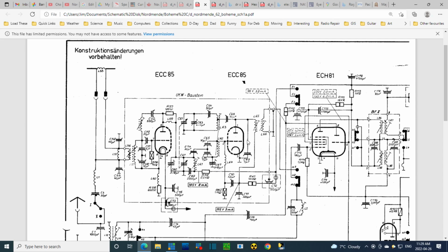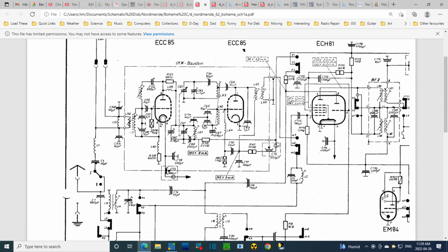Okay, so if we look at the grids back here, this is the FM tube here. So this grid is blocked here by a capacitor. A resistor just goes to ground, so there's no AVC being applied here. This one, let's see, if you go this way, I'm just looking for DC paths. There are none that way. If we go this way, it just goes to ground, and it's blocked. So no DC can be applied to these grids externally, so to speak, or from an AVC voltage.